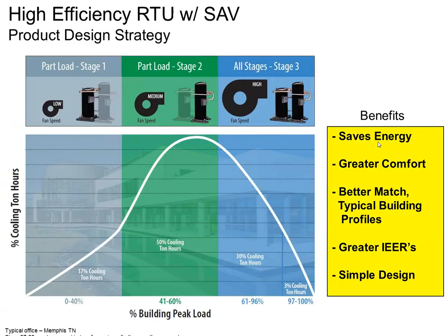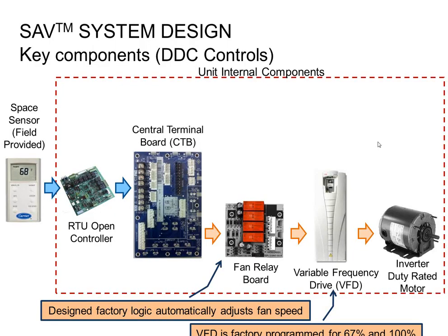You're not limited to doing this on 2-stage equipment. You can do it on 3-stage equipment or even more, but it does require you to have an economizer controller that's more robust than the standard one, and I'll talk about that in a second. But if you are able to do a 3-stage unit, it's kind of nice in that regard because you kind of get most of your bulk hours on that second stage of runtime. And very few times you actually need the 3rd stage. So it's really kind of like you got a 2-stage unit, plus you have that 3rd stage for when it really is a hot day, which hardly ever happens, but when it does, you're ready for it. So you get better comfort control, better temperature control, better latent control, and better fan savings out of the whole deal. Doing this is not as hard as you might think.